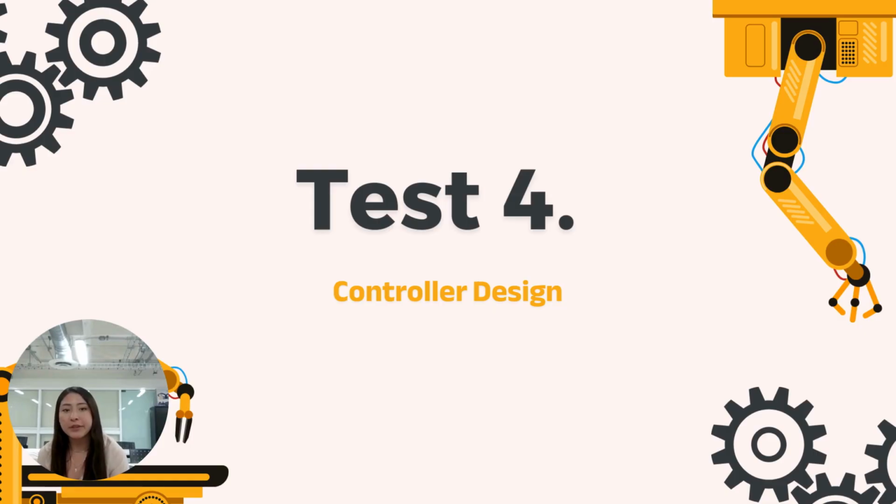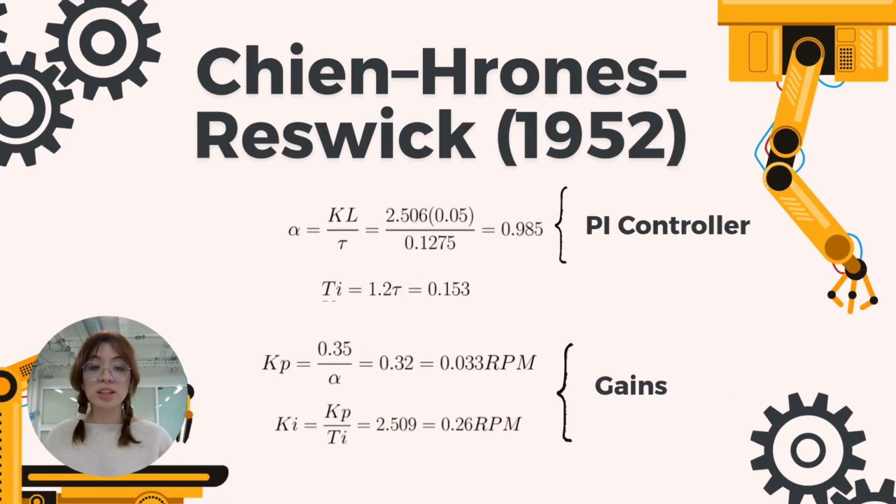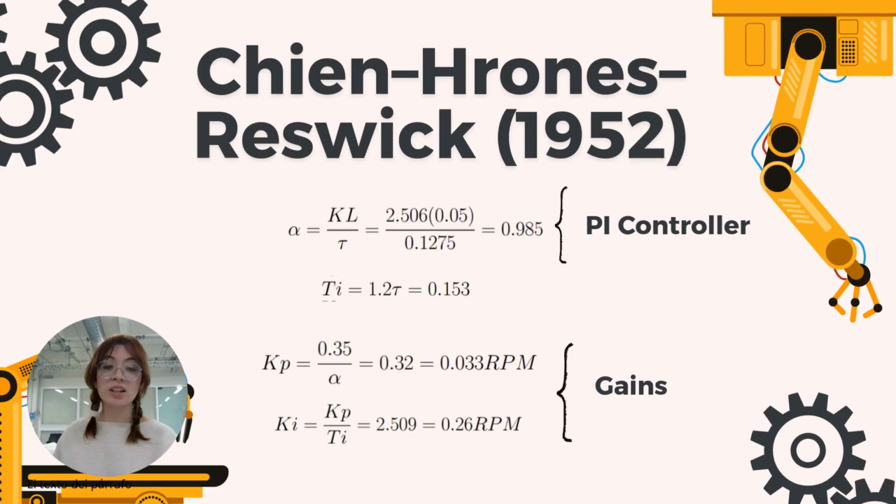With the identified model, we designed the controller. We select a PI controller, proportional plus integral, where the proportional term improves the response speed and the integral term eliminates a steady state error. We use the Chien-Hrones-Reswick method from 1952 because we know that it is more stable than the Ziegler-Nichols method. We calculate the theoretical gains in radians per second. After converting them to revolutions per minute, the gains are Kp equals 0.35 and Ki equals 0.26, which produce a significantly more accurate response on the real hardware.